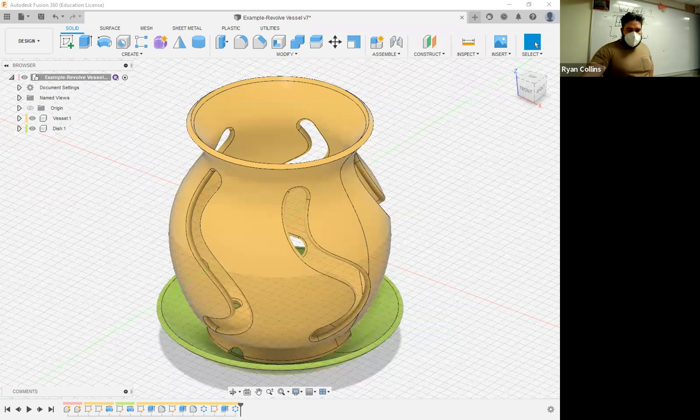Now, it's giving me a crazy error because I can't see it underneath this. Toolpath is outside. Okay, that just means I need to move one of these around. But looking at this, you can see what I mean. It creates all these additional supports so it can actually hold up the object while it's building against gravity. These are automatically generated. There are ways to manipulate them to minimize how much material you're using and all that, but honestly, they use very little material. So I just wanted to briefly show you all that. If you are interested in that, I will, of course, show you that more individually as needed.